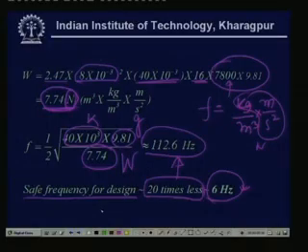you have seen that we have used the Soderberg criteria, that means variable load design. Then you have checked for the buckling, you have checked for the frequency, that is the surging of the spring. So, more or less we have seen that all the situations we have learned have been taken care of by this particular problem. So, ultimately the values we have computed in different stages are the typical spring design parameters for the given problem.